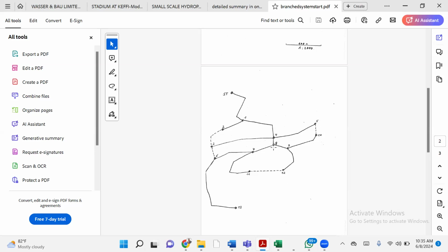So these nodes represent inspection chambers, points of intersection of two streets. It also serves as a place where you can put your water meter and measure what is going to a zone, to a district, or to a layout. It also means where you will determine the water design.